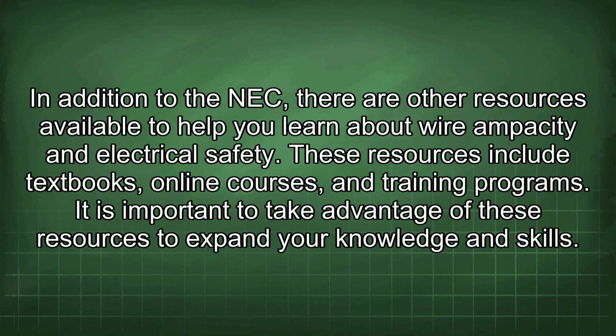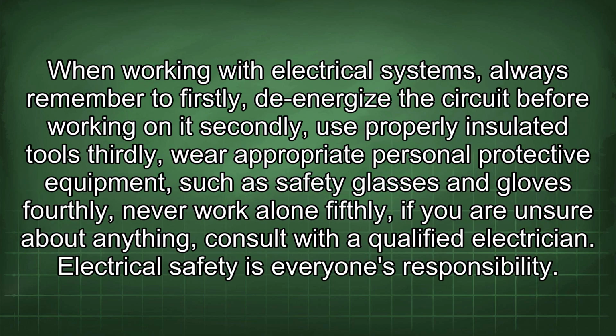In addition to the NEC, there are other resources available to help you learn about wire ampacity and electrical safety. These resources include textbooks, online courses, and training programs. It is important to take advantage of these resources to expand your knowledge and skills. When working with electrical systems, always remember to, firstly, de-energize the circuit before working on it. Secondly, use properly insulated tools. Thirdly, wear appropriate personal protective equipment such as safety glasses and gloves. Fourthly, never work alone. Fifthly, if you are unsure about anything, consult with a qualified electrician.